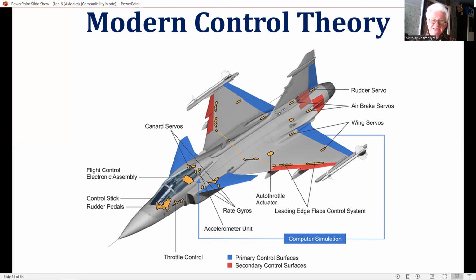For example, simplifying the pitch dynamics to a second-order system transfer function by assuming the forward speed is constant over the short period motion, deriving the roll rate response to aileron movement by assuming pure rolling motion and neglecting roll and yaw cross coupling effects. Similarly, the short period yawing motion is first derived assuming pure yawing motion, and the yaw or roll cross coupling effect neglected.